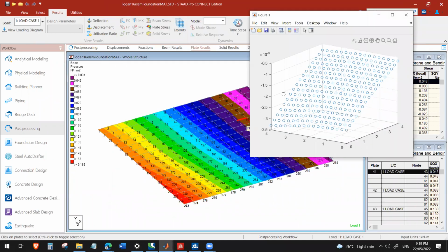So that's it. By using a thin plate bending element with 12 degrees of freedom, this shows it can be used extensively for steel plate, even isolated footing, and even mat foundation.